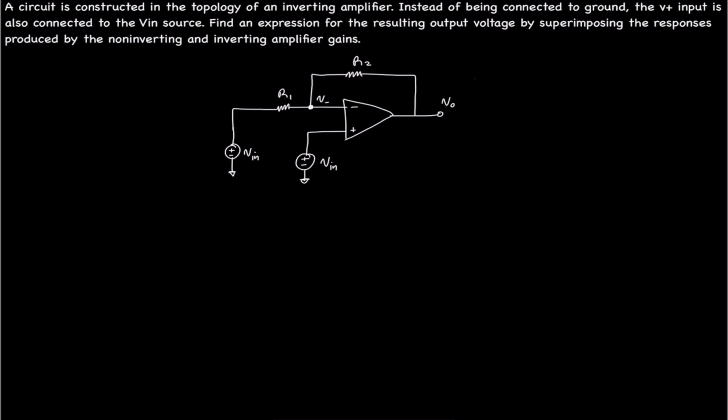So then we can start from a non-inverting topology, and by doing that, we can start from the midpoint of the voltage division. If we start from the midpoint of the voltage division, V minus, that will be inverting. For the non-inverting, we ground the end of R1 and apply the input to the V plus terminal, and that would give a non-inverting configuration.